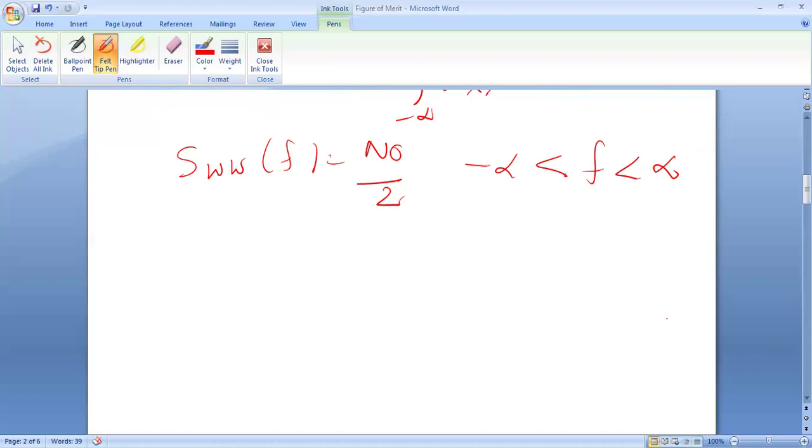With these two notations available for estimating the average power, let us slowly go into the fundamental steps in estimating the figure of merit. The first step in the estimation of the figure of merit is to draw the receiver model. This is a very important step in the process of obtaining the figure of merit. Why? Because whatever blocks are present in the AM receiver or FM receiver, not all of them contribute to the final figure of merit estimation.